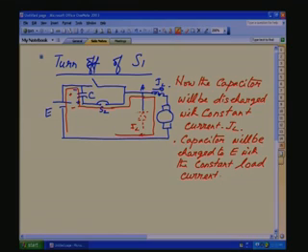Once the capacitor is charged to this point, it will oppose E, and the diode, assuming a very small voltage difference, forward biases, since very small voltage is only required. So, the diode will turn on and the load will freewheel through this path. Now, the commutation is complete.